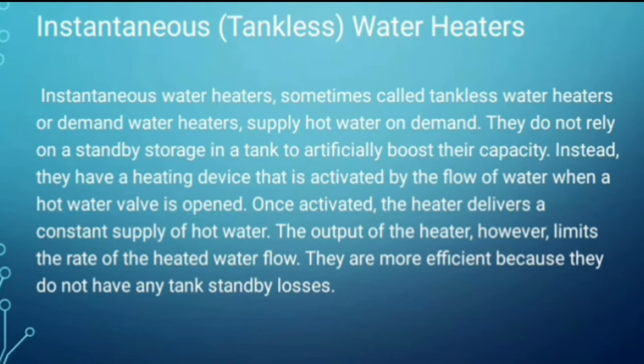Instantaneous water heaters, sometimes called tankless water heaters or demand water heaters, supply hot water on demand. They do not rely on a standby storage tank to artificially boost their capacity. Instead, they have a heating device that is activated by the flow of water when a hot water valve is opened. Once activated, the heater delivers a constant supply of water. The output of the heater, however, limits the rate of the heated water flow. They are more efficient because they do not have any standby losses.